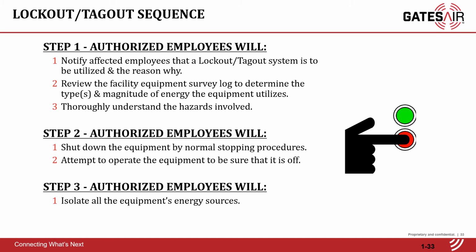Shut down the equipment by normal stopping procedures and attempt to operate it to make sure it is fully turned off. Then isolate all the equipment's energy sources.